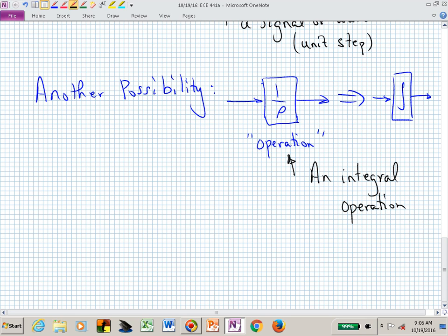And what we are going to find as we move through the class is introducing integrators can really be beneficial to our system, but there's a trade-off. If you put a pole at the origin, how stable is that pole? Marginal, isn't it? It's on the stability boundary. So why are you putting things that are marginally stable into your system? Why would you want to introduce an integrator?